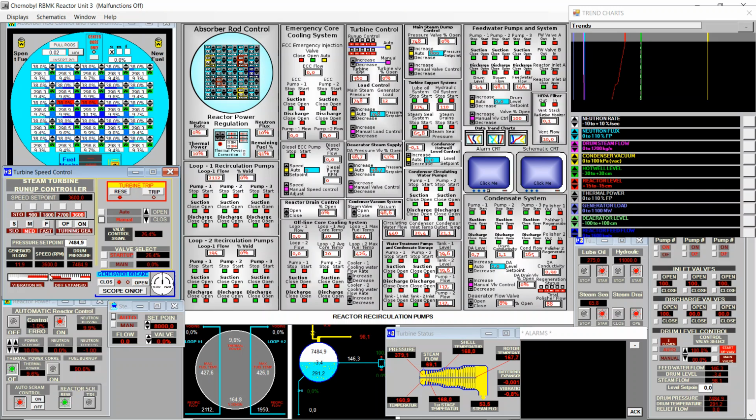Slowly. Why this? Because if we are at a generated load of 12 megawatts and we go offline by opening the brake, it's like driving on the highway at a constant speed, where the engine is at a given load given by our throttle, or by cruise control, and then suddenly we press the clutch. If we don't change the load and we press the clutch suddenly, the engine will rev up and go to red line in a very few seconds or milliseconds. So here it's the same.